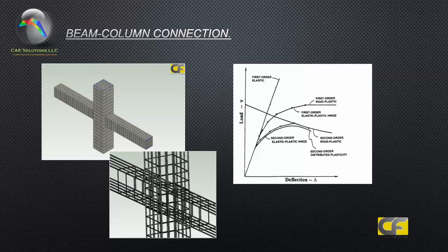On concrete frames, the stiffness of members is very sensitive. Thus, the joints are affected by concrete cracking and bond slip, for example, and the post-yielding response of columns and joint panels is very sensitive to axial load. Under large deflection, inelastic cyclic deformation, component strength often deteriorates due to fracture, crushing, local buckling, bond slip, and